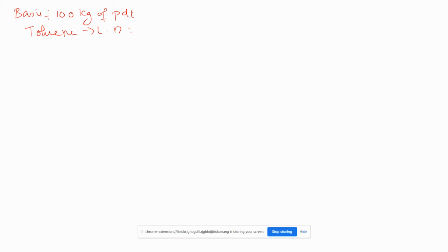Now we have to find the percentage excess of nitric acid. You people know the formula, so accordingly we have to find the percentage excess. For that, first we will write the relationship between nitric acid and toluene. 1 kilomole of nitric acid is equivalent to 1 kilomole of orthonitrotoluene, and you should know the molecular weights.